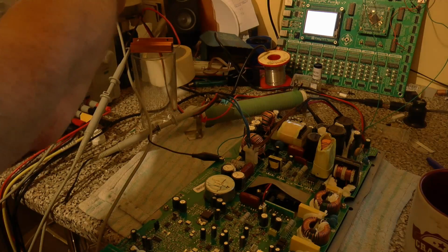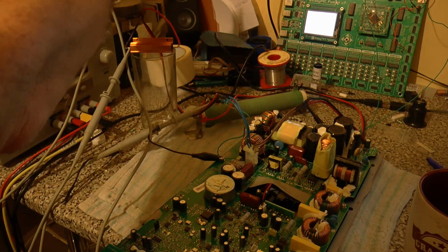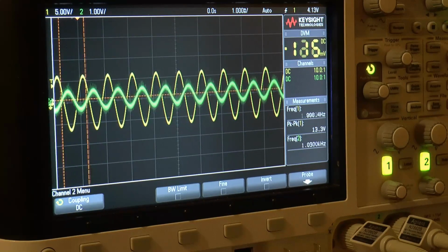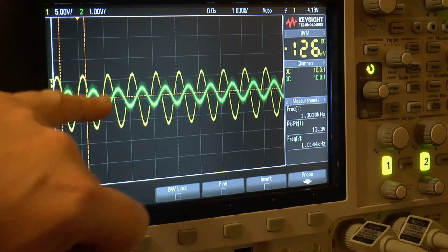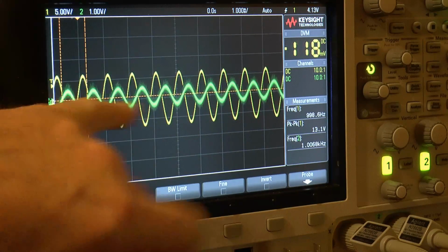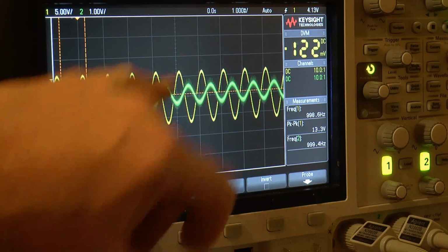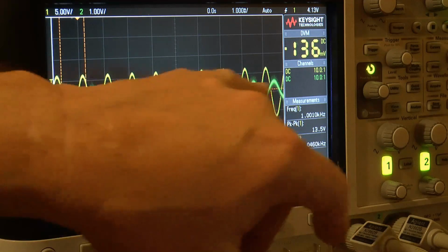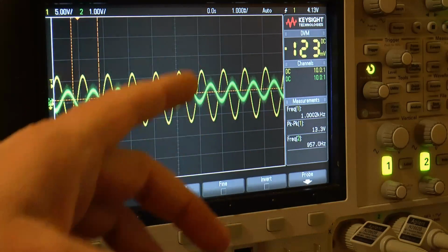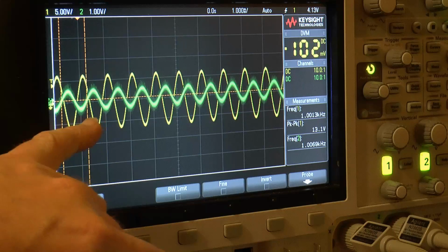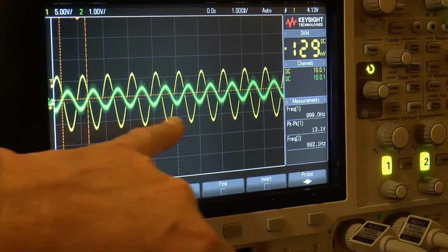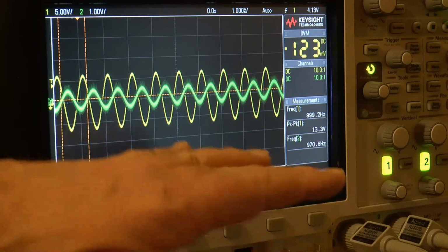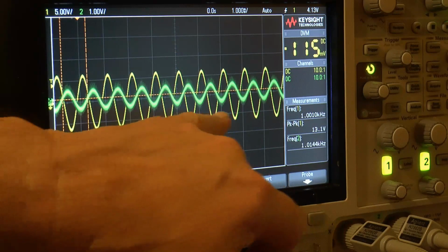So now if I turn this second channel on, as I was ramping up the frequencies, obviously the treble in green doesn't do anything sort of below 1 kilohertz. It sort of starts peaking at 3.8 kilohertz, and again at 16. And obviously this bass, which is the yellow one, drops off 15 to 2 kilohertz, and there's nothing at 3 kilohertz.